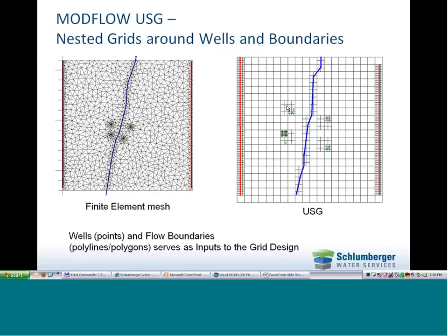Another question that came in: what are the available two-way boundary conditions? I'm not sure what you're asking there, but essentially Modflow LGR supports all the standard flow boundaries like your river, lake, constant head, and drain packages. The boundary condition that is generated after the LGR is run is a package, as I mentioned, .bfh, which contains the heads and the fluxes at that interface. I believe the only restrictions, as I mentioned previously with LGR, are that the transport package is not supported, and I believe there are some solvers that aren't currently supported.